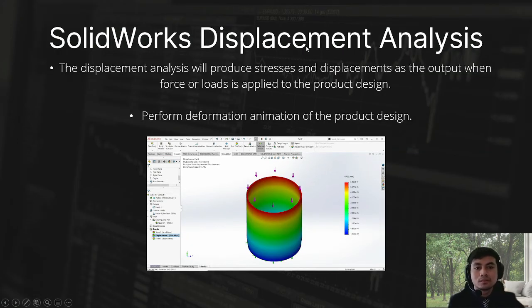Next is SolidWorks displacement analysis. The displacement analysis will produce stresses and displacements as the output when force or loads are applied to the product design. It performs a deformation animation of the product design. So this is the result of my displacement analysis on the reservoir tank.